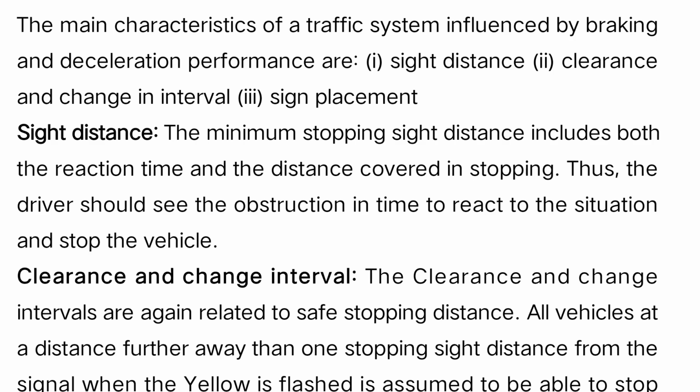Clearance and change interval. The clearance and change intervals are again related to safe stopping distances. All vehicles at a distance further away than one stopping sight distance from the signal, when the yellow flash begins, are assumed to be able to stop.